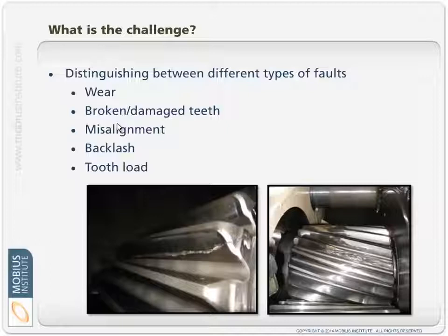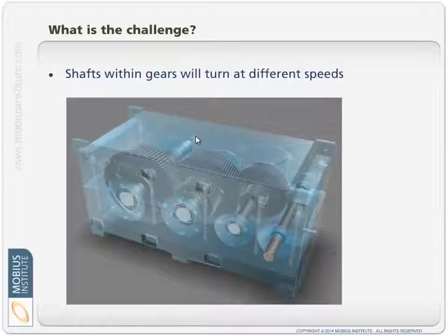In any case, we're looking for those different sources of vibration that indicate these different types of faults, and we've got time waveform analysis and spectrum analysis at our disposal, and you want to make sure that you use both techniques. That is probably the most important message out of this. You need to do time waveform analysis, and I know I mention it later, but you should also be performing oil analysis to make sure the lubricant itself is good, and wear particle analysis to see if there are any signs of wear. Anyway, let's move along.